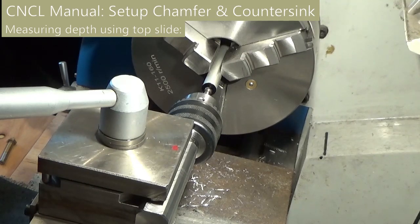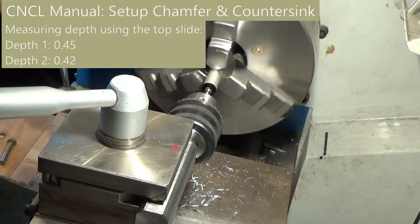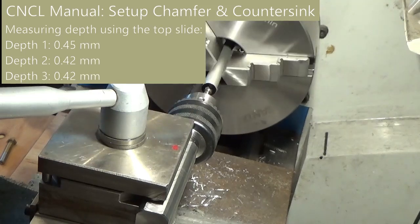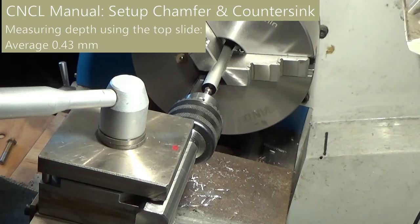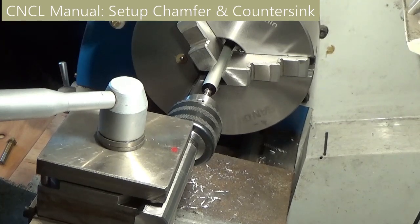I can now measure the depth using the top slide. I find 0.45 first value, 0.42 second value, 0.42 third value. So the average is 0.43 millimeters. We move the tool back to the home position.